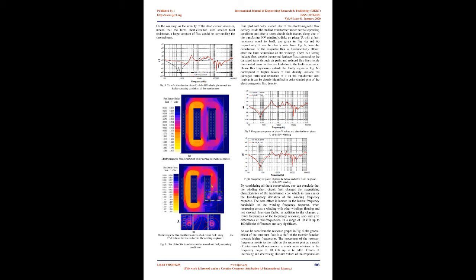Table 2 shows the correlation and spectrum deviation between the faulted and non-faulted responses of three phases of the transformer HV winding, corresponding to the graphs shown in Figs 5, 7, and 8. Table 3 illustrates the results of applying the indicators to the normal and faulty responses of phase U of the transformer taken by HV, LV, and interwinding measurements. Table 4 shows the correlation and spectrum deviations between the baseline measurement of phase U of the HV winding and 4 measurements made during the fault occurrence with different severity levels on the same winding.